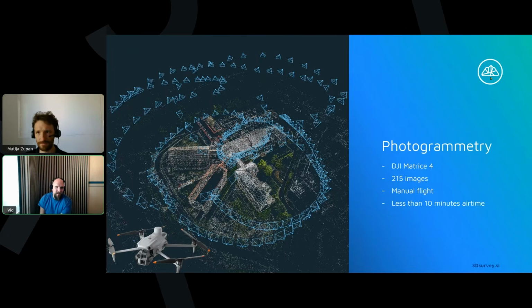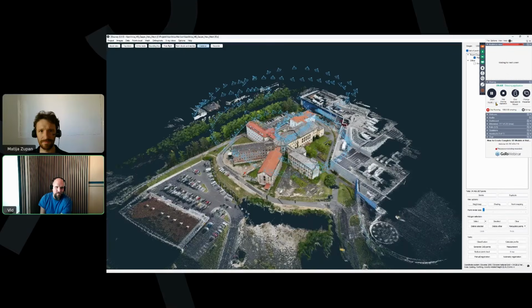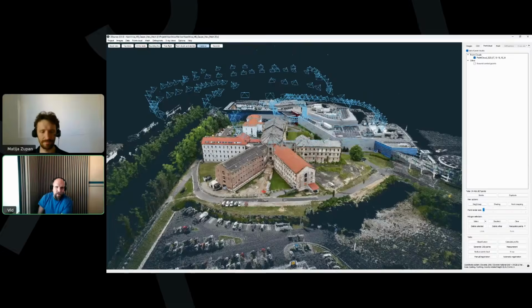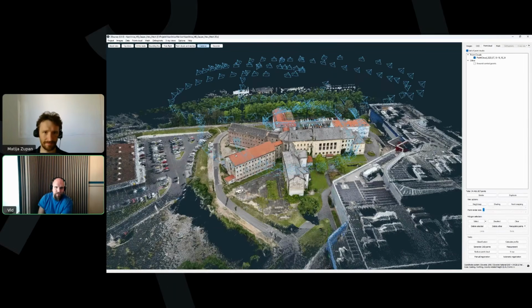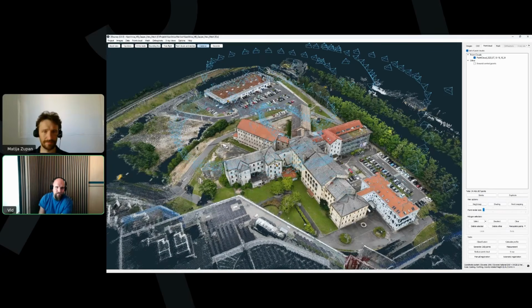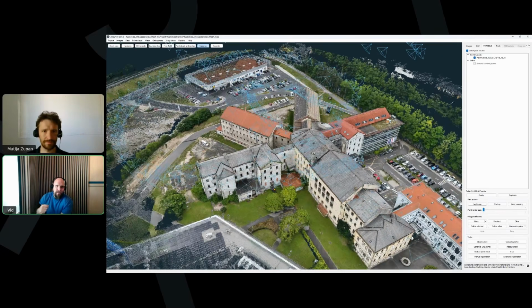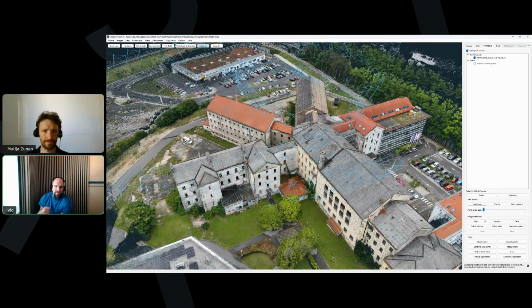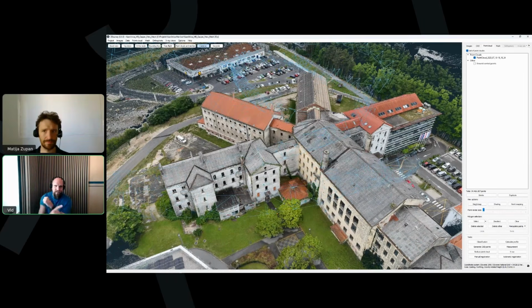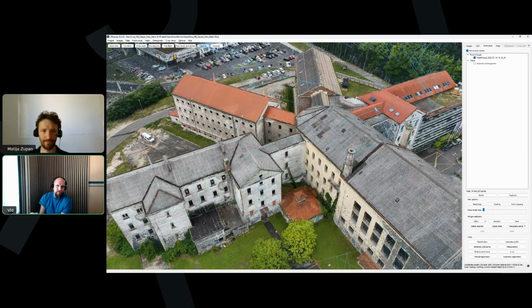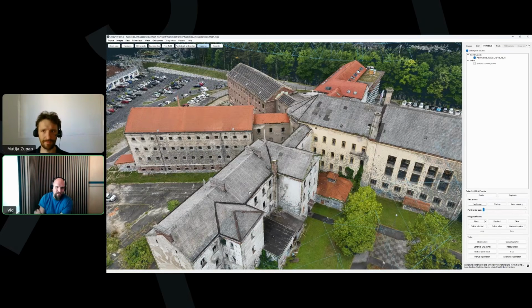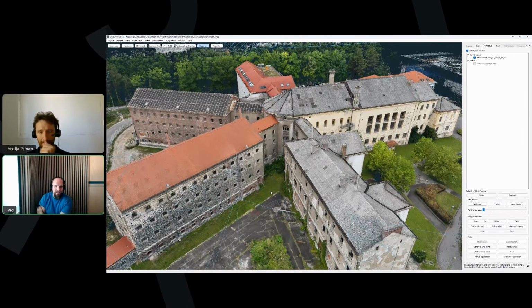So if I just add my 2 cents, I think a good option for mission planning here, also a very powerful thing, could be just to fly in the orbit mode, where you fly the drone to the middle of the point you want to record, select orbital flight, move the drone out, and when you move the joystick to the left, the drone starts to make a circle to the left, so you don't have to think so much about all the navigation, how to put both joysticks. You just do everything with one joystick.